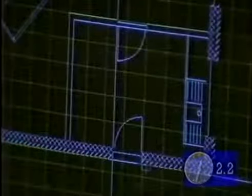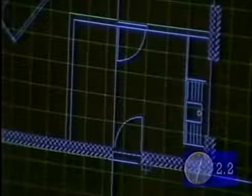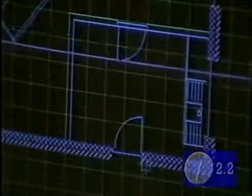So we've got a window over here. Again, J option, and place it in there. And really we need to do the doors now as well. So again, select it from the menu. It's another symbol for the door opening. Select the wall, J option again, and again point to the jamb where I want it to go in. Now these door openings and the window openings could be variable as well. These have been previously defined.